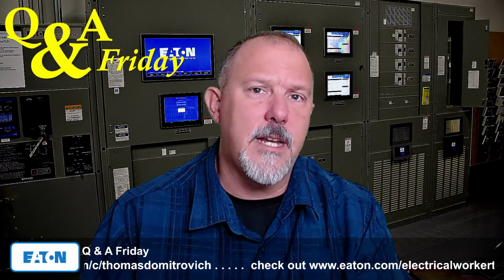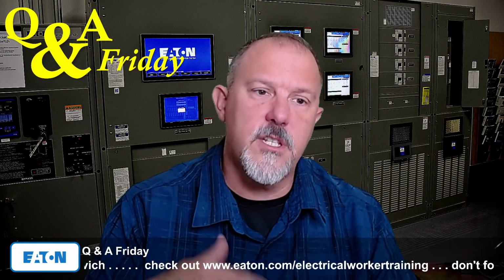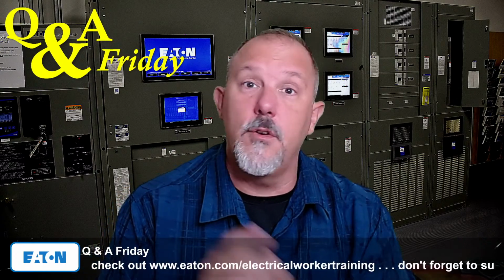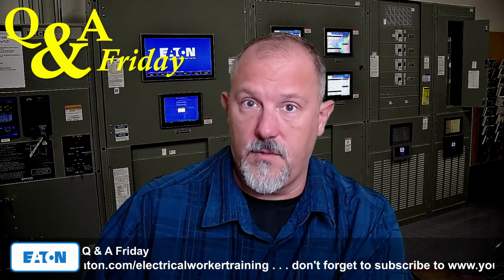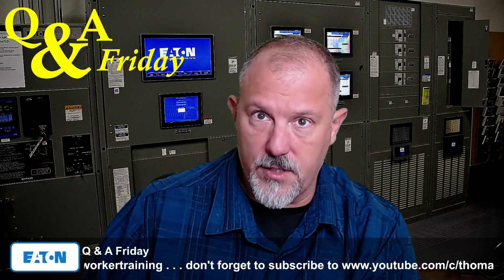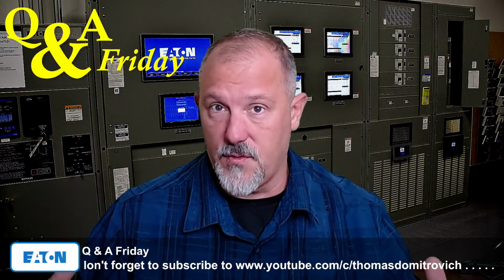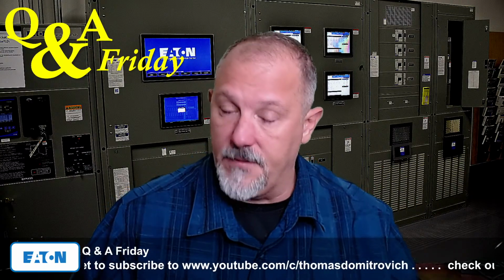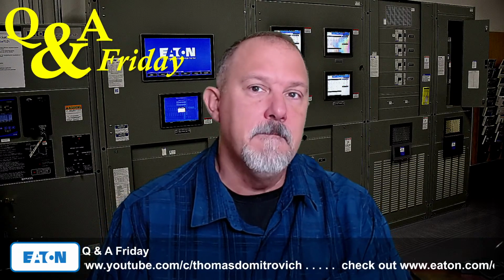If you're applying differential protection and those additional levels of protection, you're doing that because of your investment, in my opinion, your investment in the transformer. We're not going to do differential for control power transformers, but we will probably do that for very large transformers that you've paid a ton of money for. Because it provides an additional level of protection, in my opinion, over and above what's required by the code.